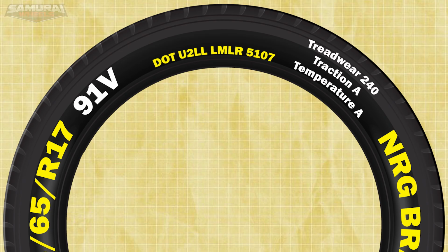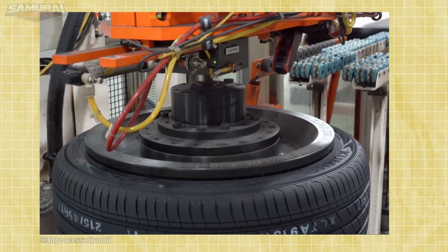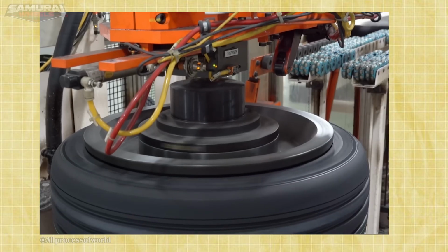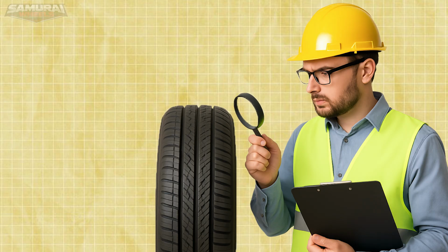Each tire manufacturer may assign these codes as they see fit, provided they maintain a consistent and explainable system within their coding. After the size code, the next sequence in a DOT number consists of 3 or 4 digits that designate the tire type. This coding, though optional, is widely used by tire manufacturers for internal tracking purposes, such as managing returns and quality control, tread design, construction, and other tire-specific features. The decision on how exactly to code the tire type lies with each manufacturer, leading to a variety of coding systems across the industry.